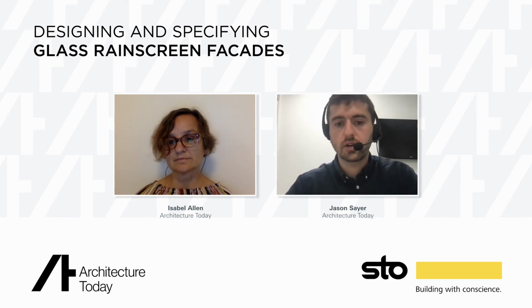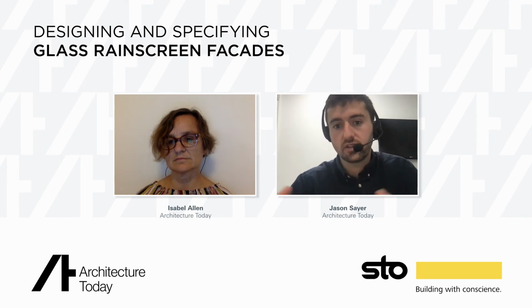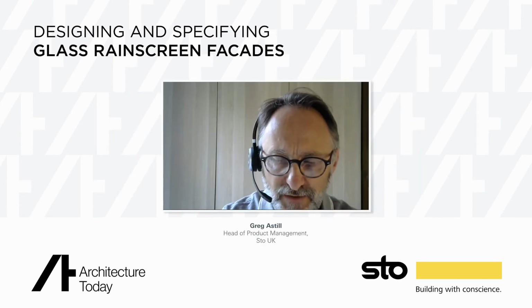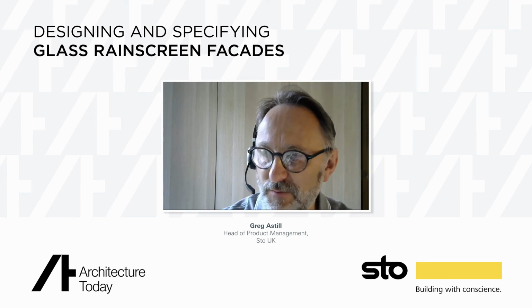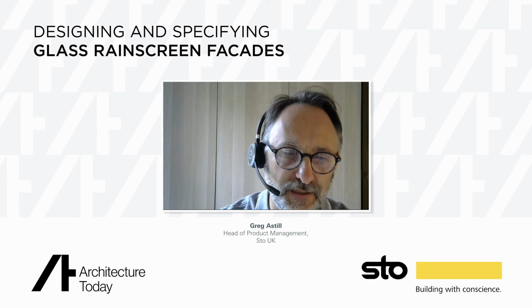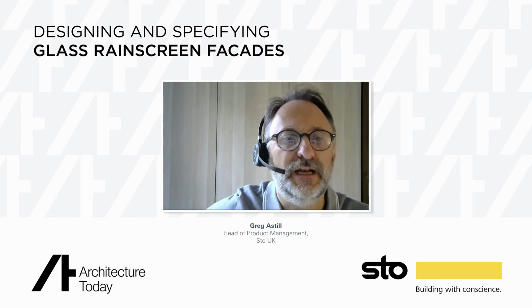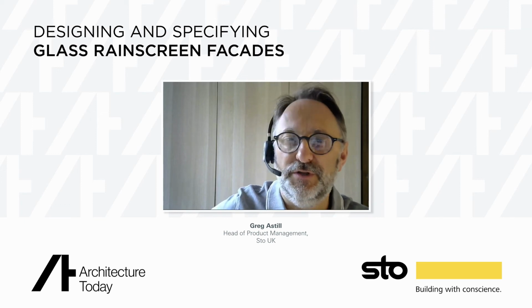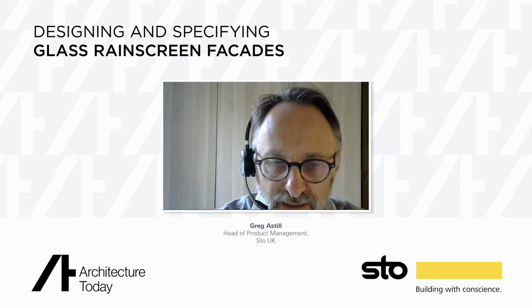So it's interesting you talked about moisture there, because there's a question, again relatively general: what are the chief moisture control challenges when integrating a glass Rainscreen facade into one's design? Certainly. As part of working together with a designer, we'll perform the U-value calculation that also contains a condensation analysis. So we'll ensure that we're not going to get any condensation in the wall anywhere.